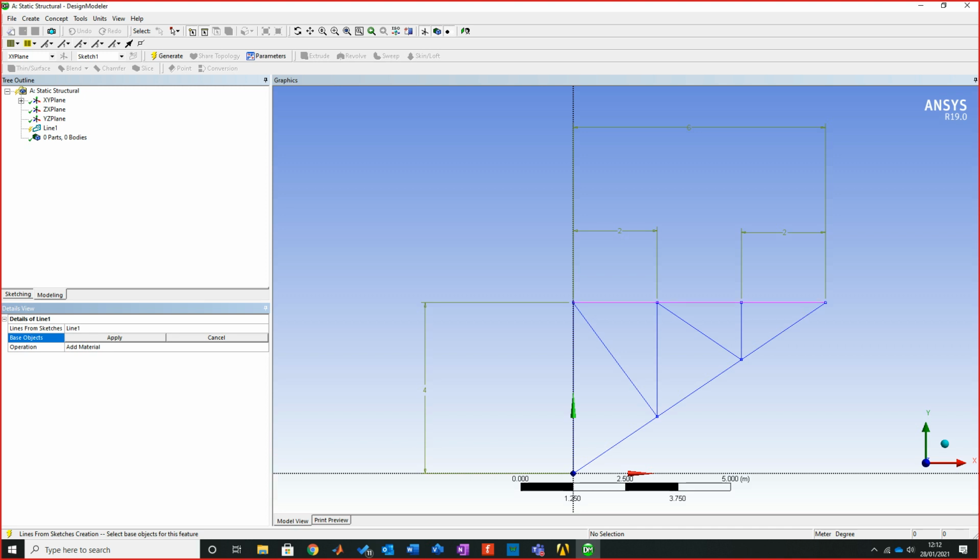What you're actually looking to do is select them all in one go. And this comes from anybody who has got a lot of experience in CAD. You'll always know, if you want to select an entire sketch in one go, go to the design tree. Click on the sketch. Everything's selected in one go. If you try to click on the screen itself, it's going to pick up individual members, then you're going to press Control, try to select all, and you sit there for ages, wasting time. Use the design tree. It's a great way of being able to execute exactly what you're doing.